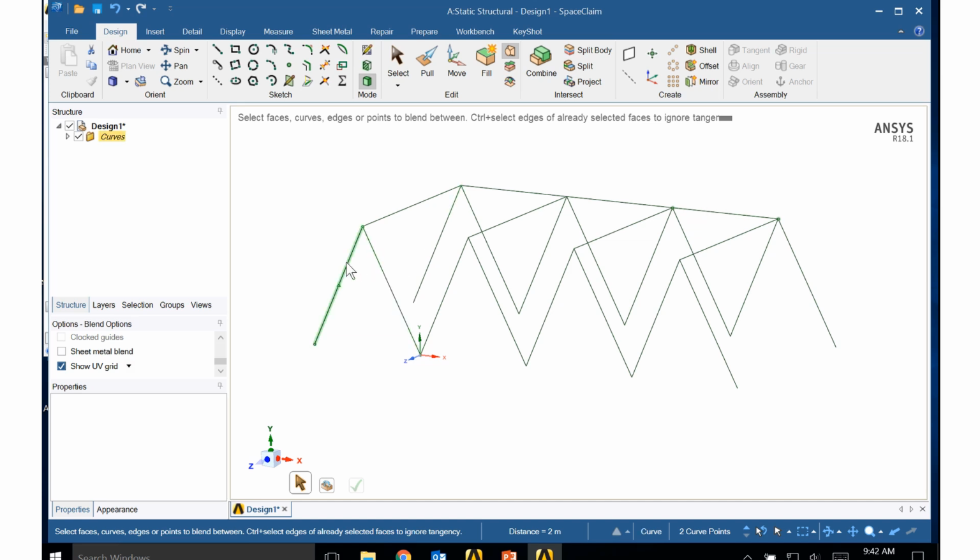Now when I come over to do the lines here, I need to be careful. When I select this top point here, you can see this line here is highlighted. And so I'll click on it, and then when I come over here to click on the point, I just need to control click, and this line is highlighted. So control click, enter. Same thing, click, control click, enter, click, control click, enter. Now I could have developed a lot of those lines with copy and paste.